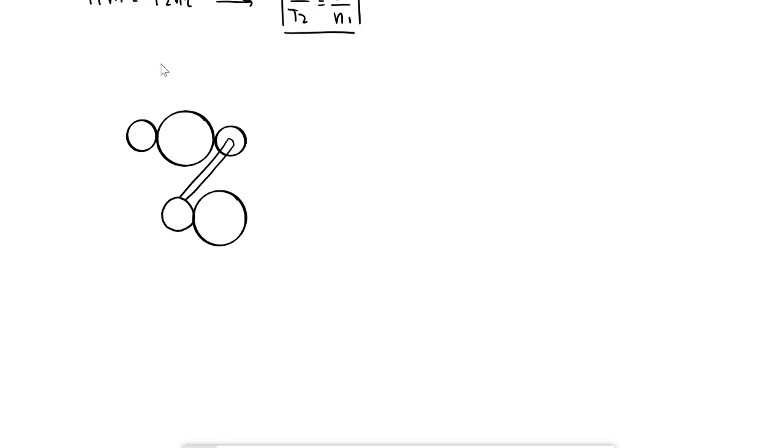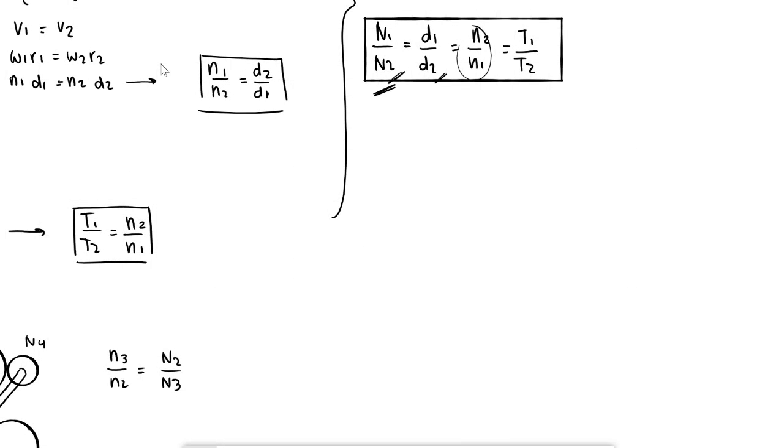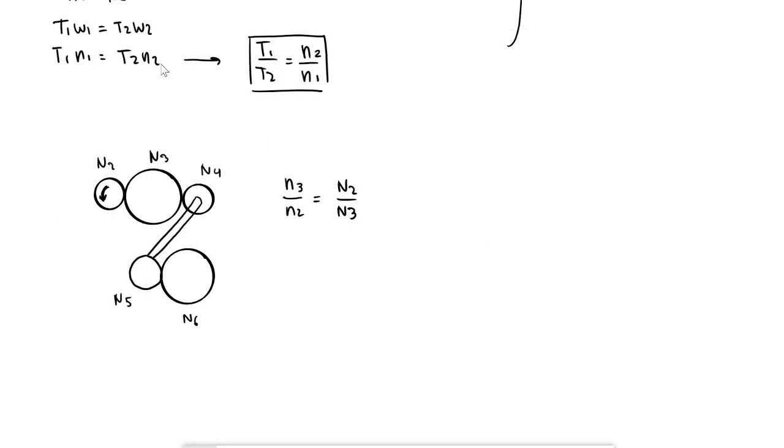We can either have the number of teeth, so the information would be, for example, n2, n3, n4, or the diameters. It doesn't matter, and you're always going to be able to count the number of teeth, or to have the pitch diameter of the different gears. So if n1 and n2 is what's driving everything, I can do a simple calculation of the speed of 3 with respect to N2. So basically I'm just using this relationship between number of teeth and speed.